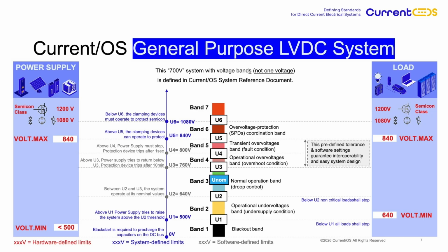In a DC microgrid, which is naturally isolated from the public grid by an AC-DC converter, startup poses unique challenges. In AC systems, powering up a building involves carefully managed steps. Magnetizing the transformer, progressively energizing circuits, and bringing loads online gradually to avoid tripping protections due to high inrush currents. DC systems require a similar approach, albeit on a smaller scale due to limitations in the nominal power of the AC-DC converter and the available sources.